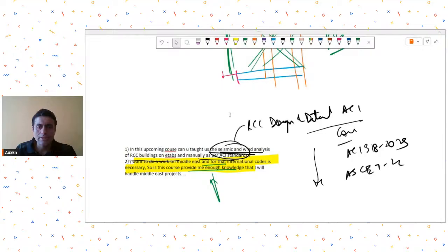So Mr. Vineet is saying if the water table is high, you need to reduce the pile capacities as given in this table 1 by 75%. Oh, I didn't know. Thank you so much. I have been using this table for more than 10-15 years, but this thing I didn't know till now. Very interesting.